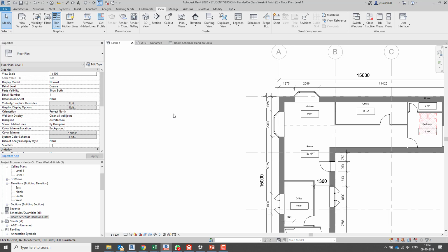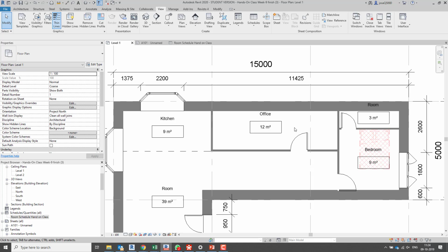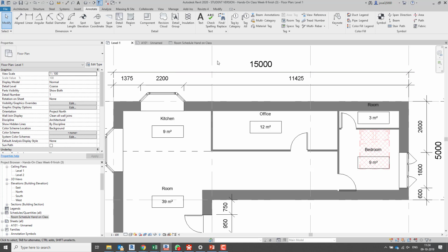Okay. Now I'm gonna start to document my drawing, and I want to explain what this wall is. So I'm gonna come to annotate. Remember, at this point, I'm doing something on the tracing paper. I'm not changing the model. I'm just using a tracing paper layer on top of my 3D model. You guys remember this explanation? Yeah. So when I'm on the annotate tab, I'm working on that layer. It's view specific. It doesn't affect the model.